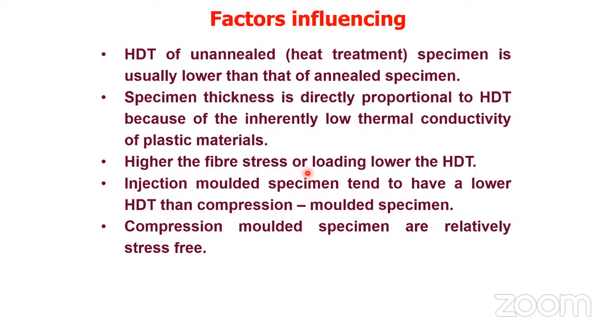Okay. So injection molded specimens tend to have a lower HDT than compression molded specimens. It again depends upon the packing of your polymeric system. Okay. Accordingly, with the packing density, your HDT will change for the same material I'm talking about. Okay. Then compression molded specimens are relatively stress free. Okay. So these kinds of factors generally affect your heat deflection temperature.